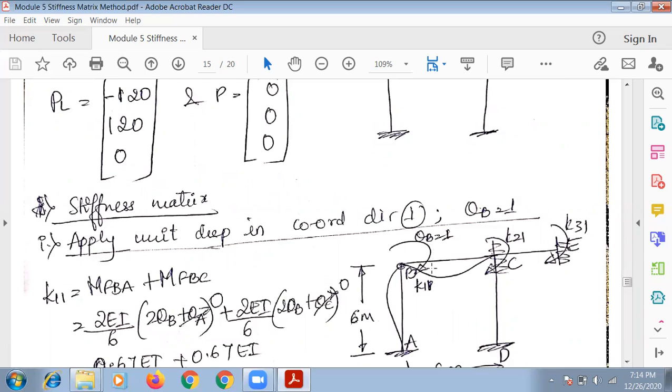Next, the same moment tries to push BA to the left side like this. It pushes like this and goes on top. That's why this will bend. Again, you can notice the bend is more here, and as it comes towards the fixed support, it goes on reducing. You can see it will be straight up to a certain portion, then it bends. Here also it bends. So once you mark this, next is one marking. This is very important: the deflected portion of the beam.